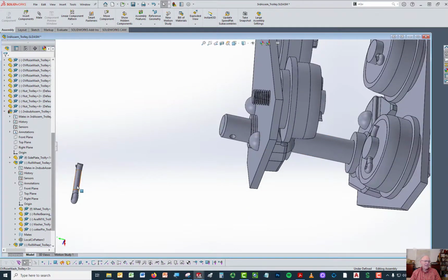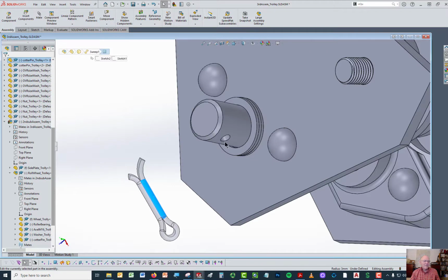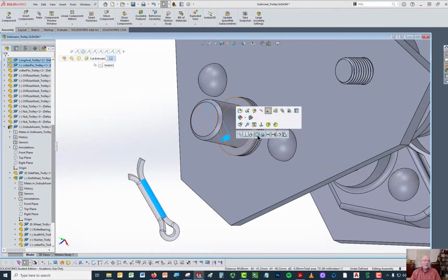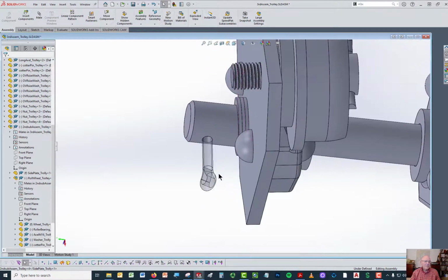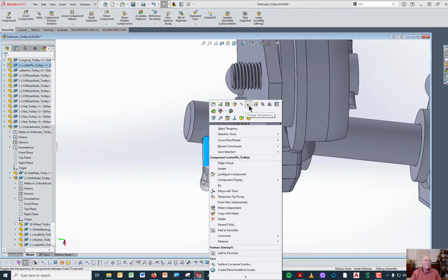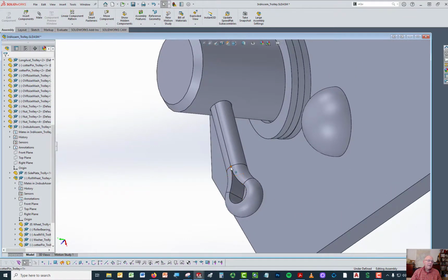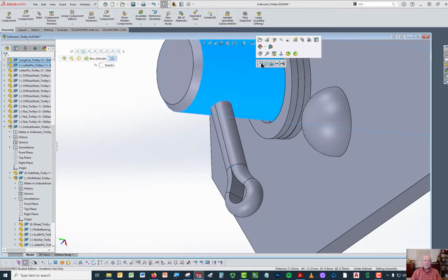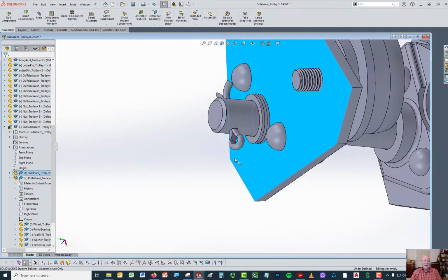The cotter pin. So we're going to bring the cotter pin over. I'm going to put the cotter pin in, it doesn't matter which way we do it, so that the body of the cotter pin and the hole are concentric. And I'll do the same thing I did before. I did not mean to make that invisible. I must have picked the invisible button without noticing it. Now I'm going to do the same thing I did before. I'm just going to take that point right there and make it coincident with that surface, which means it won't go up and down, but it's still free to turn, which it has to be. Now, I'll back out just a little bit, and I'll turn that, or I can just barely see it.